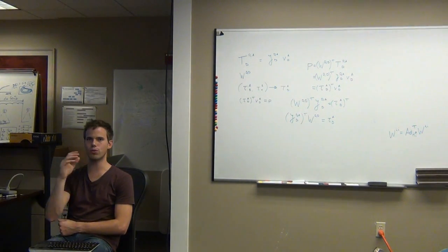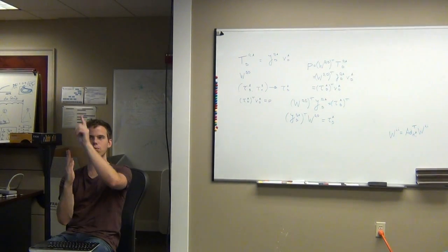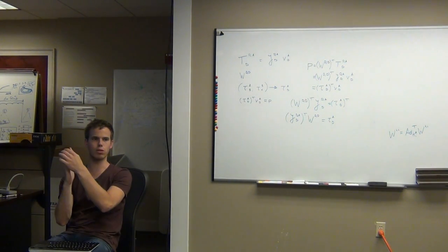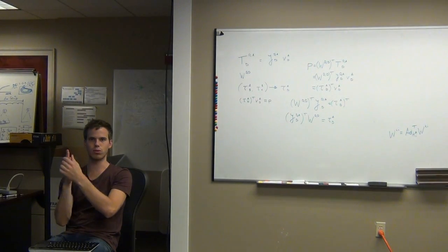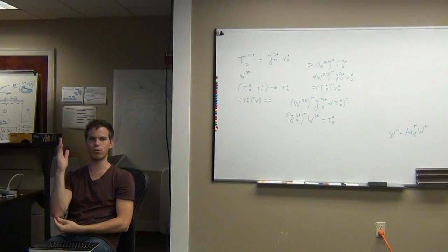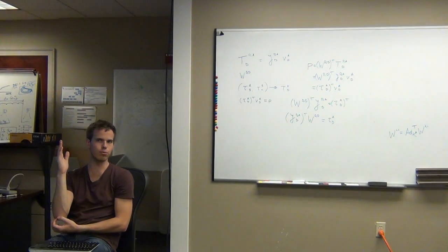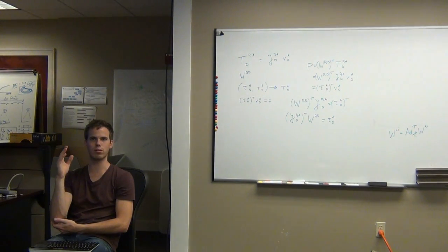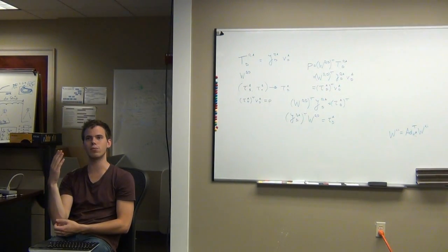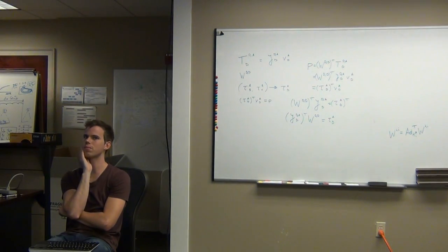So if you're trying to pull on the end of the pendulum in that direction, then J transpose F is just going to result in 0 torque, because of the way your joint constrains motion, you don't have to exert any torques to have the same effect as that wrench. Right, because that wrench would have no effect.